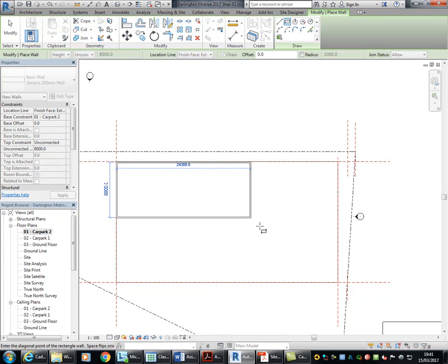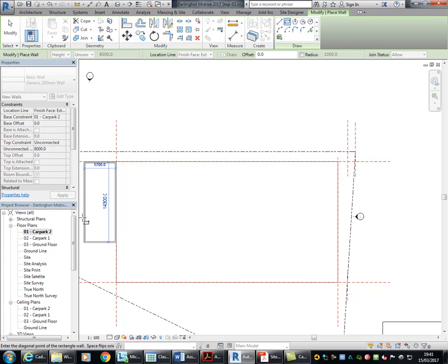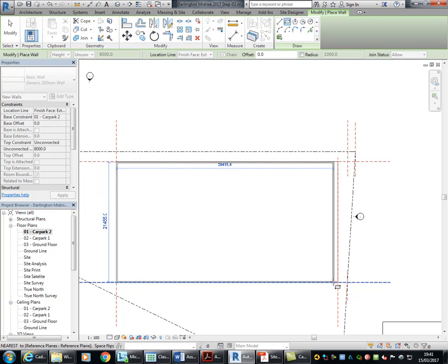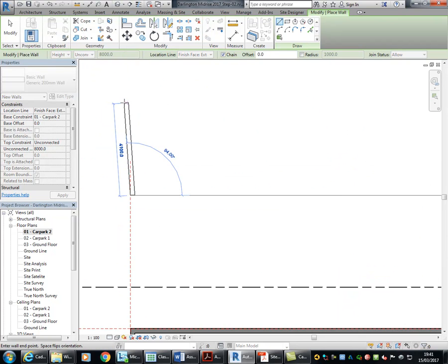And so there, you just need to make sure your walls go the right way. Notice how there the walls go inside, but if I go in different directions, well, with a rectangle it's pretty straightforward, but when you're using other options, you might see that the wall goes to one side if you go one direction, but if you go the other direction, the wall's going to go the other side. So watch out for that. And really, that's what you get.